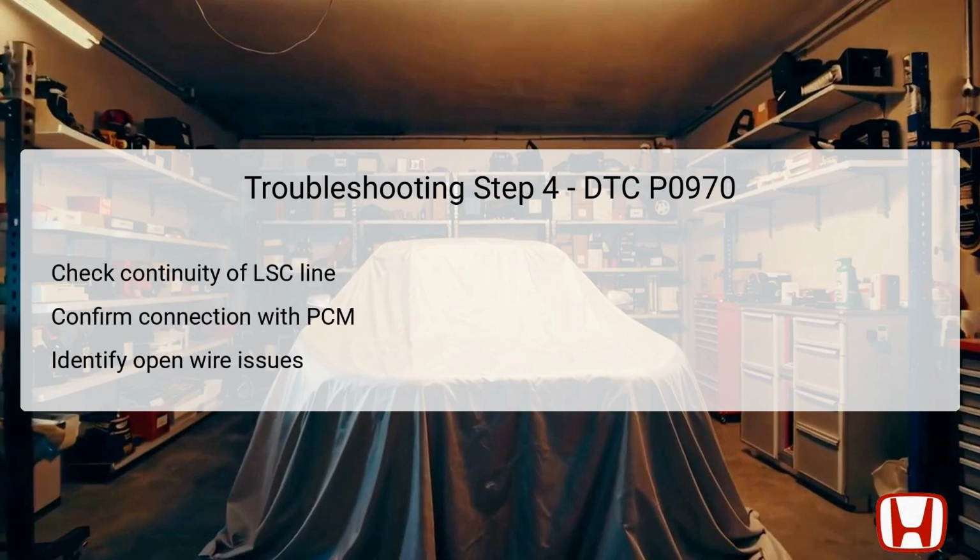During the fourth troubleshooting step, you will again start by disconnecting the AT clutch pressure control solenoid valve C2P connector. This step ensures that you can conduct an accurate continuity test without electrical interference from other components. Once disconnected, check for continuity between the set test points. This step checks the integrity of the LSC wire, which is crucial for the proper operation of the solenoid.